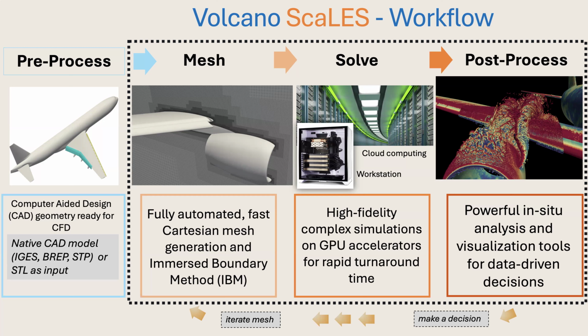In a couple of minutes, you can run the surface mesh required for billion grid points for volume. And then automatically, based on the user's input, the volume mesh is also generated in 5 to 8 minutes for multiple billion grid points.